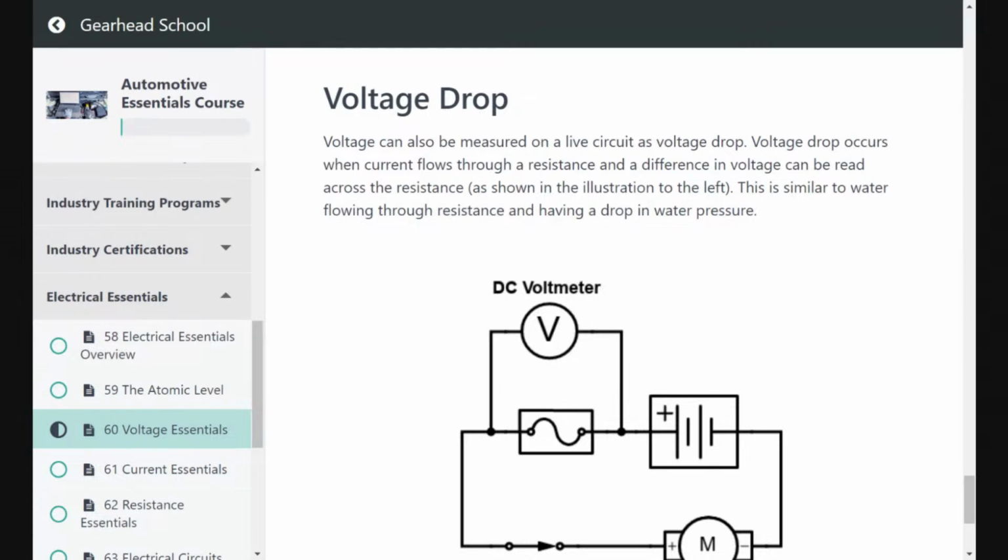That's called a load. If you have one load on a circuit, all the battery source voltage should show up at the load. Anything that you lose getting there on the power side or getting back on the ground side is going to be robbed from the load itself, and it's not going to perform as planned. Now this is showing a voltage drop, so you can take the same voltmeter that you check source voltage with and go out on the circuit and check for voltage drop.